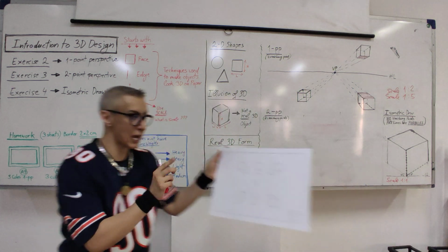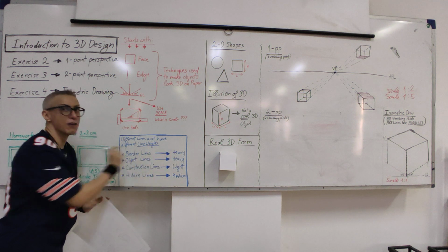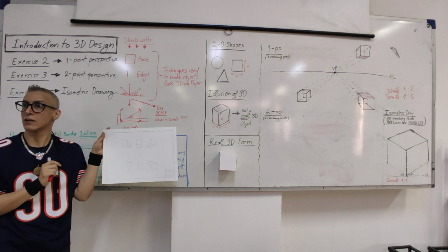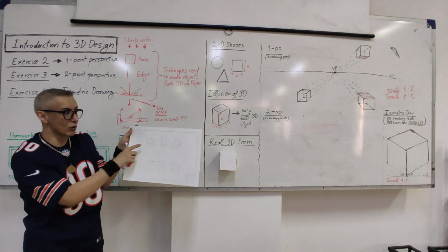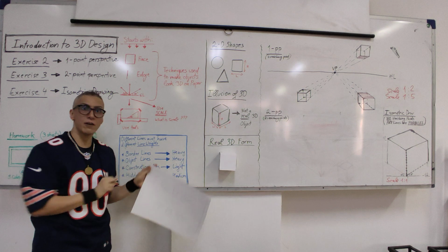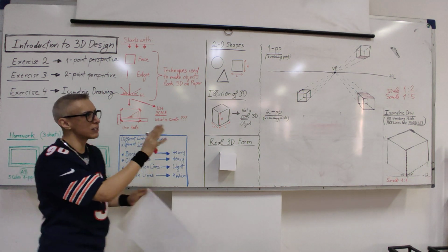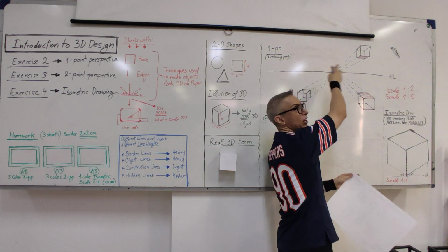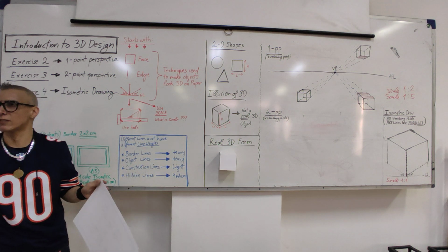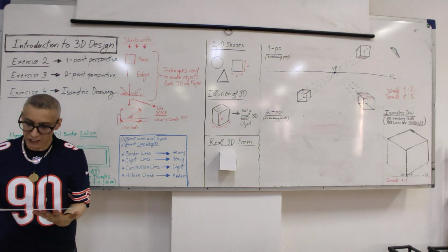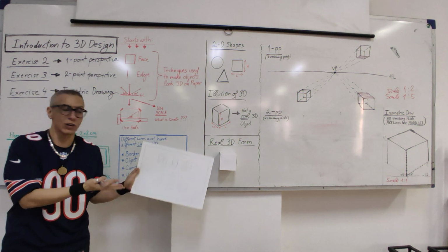We have on the paper, you will have a border line. You see border lines, which are these. They have to be heavy, visible, okay? The object lines are the outside lines of the object. They also have to be heavy so that it stands out from the paper, okay? The construction lines, any lines that you use to construct the object, should be light. The lighter, the better. So when I look at them from here, yes, I see them, but I don't want them dark and heavy and black, okay?